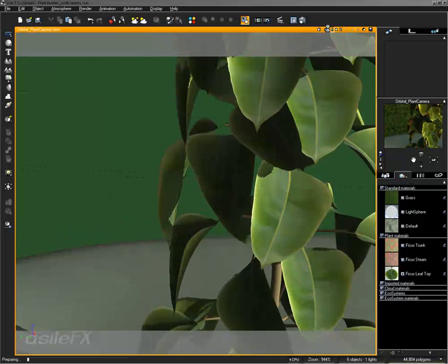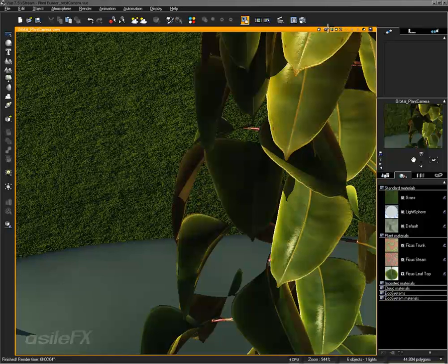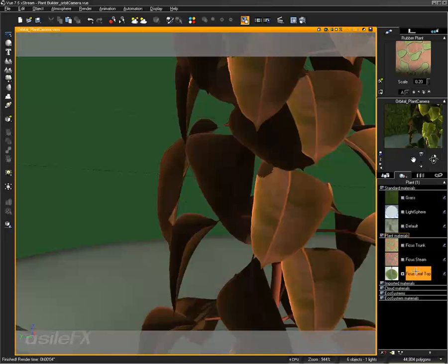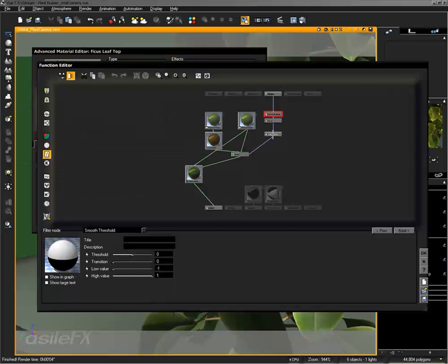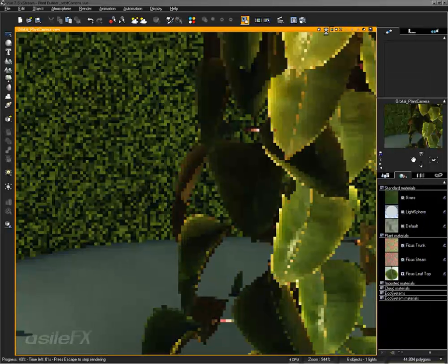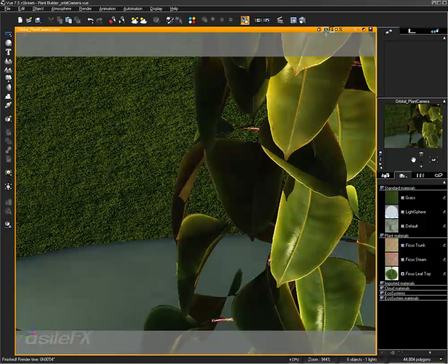I'll go ahead and zoom in. Since I'm using Orbiter, I don't want to move the camera because that'll change the pivot. So just zooming in and out will work. You can see the harsh lines are pretty clear now. So all we need to do is just use that threshold and really fine-tune that setting. I've been using 0.65 or 0.6, sometimes going a little bit larger to get a nice blend or fade. Now it will start to transition into that color, but it won't be a harsh line at least.